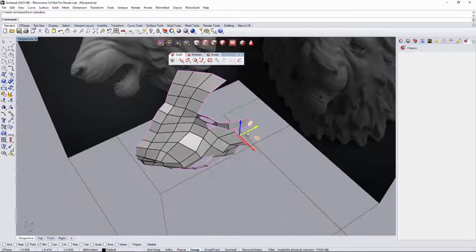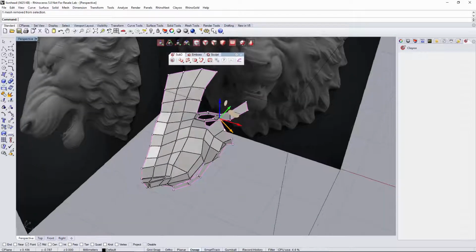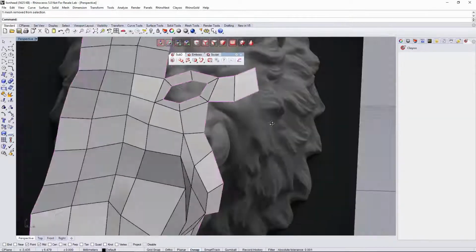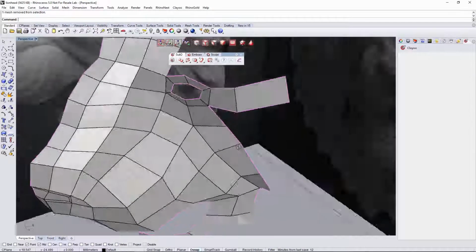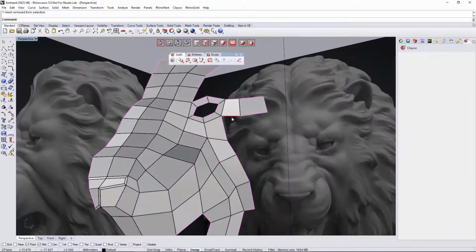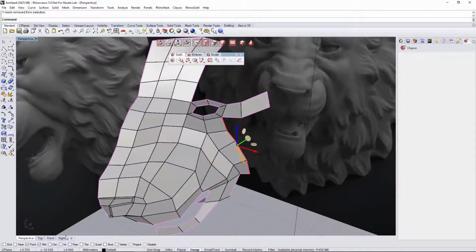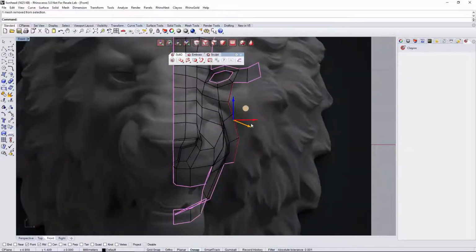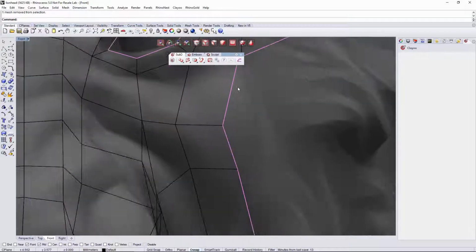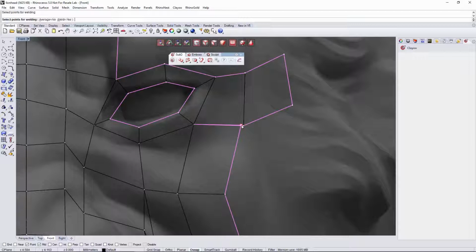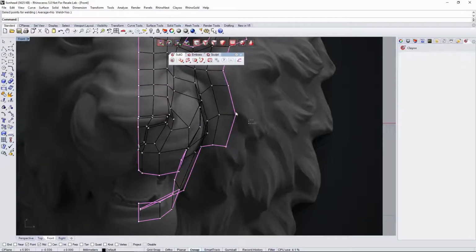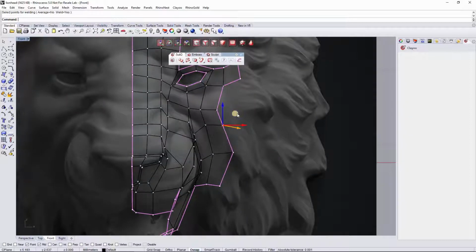So selecting, moving it outside a little bit. This part has to go even more outside. Select these parts, add face with the A, the pen face tool. We're gonna have to do the same for this other division. So holding Alt like this, and from the front view, making sure that it goes to the outside, and welding from this point to this point. We are welding to the second point because this is the one that we extract from the eye, so this is the correct one. So the one that we are sure that has the correct position.